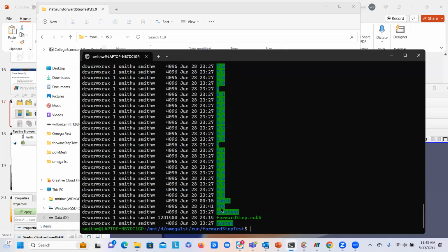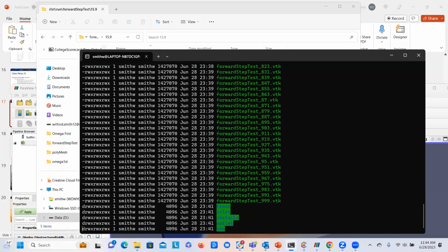And there is that one directory called VTK, which is where all of the output files are. These directories here are the baseline directories that contain OpenFOAM formatted output, and that VTK contains all the directories that are compatible with ParaView post-processing.